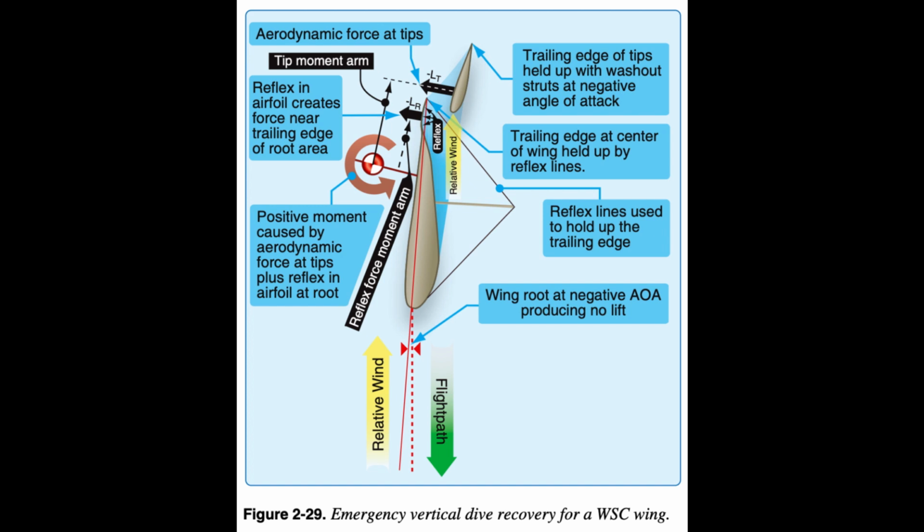Reflex also provides a stable pitch-up moment for an airfoil when it is flying at normal flight angles of attack. The greater the reflex, the greater the nose-up moment of the airfoil. This is used in some WSC airfoil designs and also for trim control, as discussed in Chapter 3.